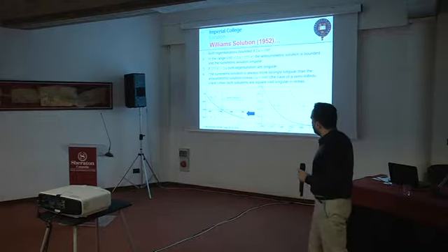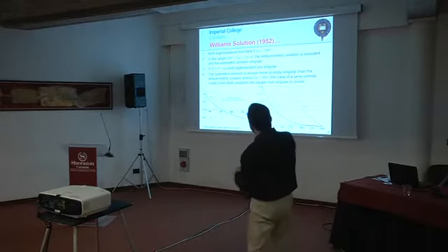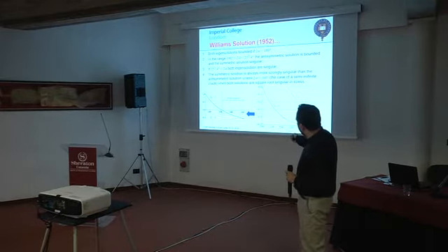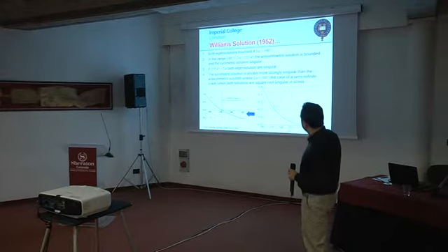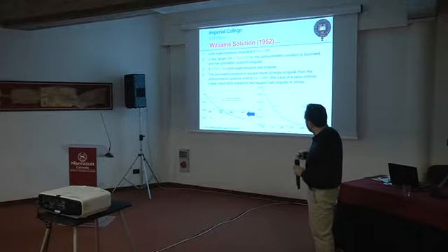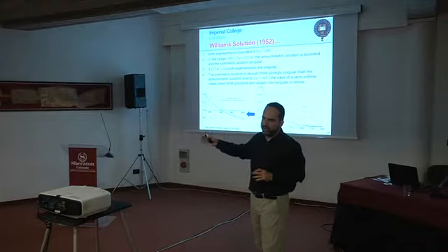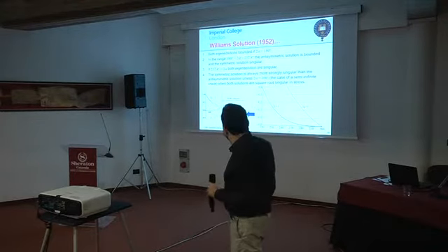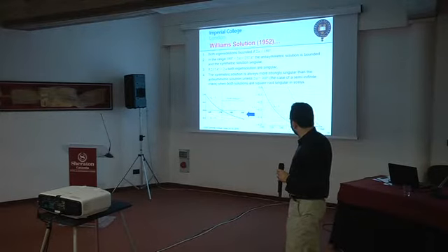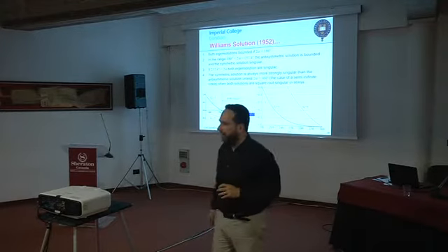And that is exactly what the next slide says. Sorry, 257.4 is the angle, but basically, obviously both eigen solutions are bounded if you have a flat sample or a re-entrant notch. So anything below 180 really is not singular. Anything that is between 180 and 257.4 is singular in mode 1, bounded in mode 2. Everything that is beyond it is singular for both.